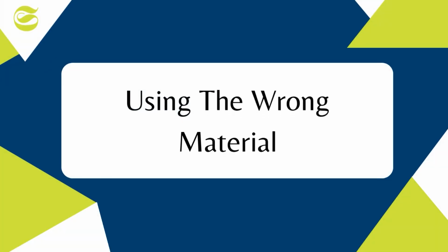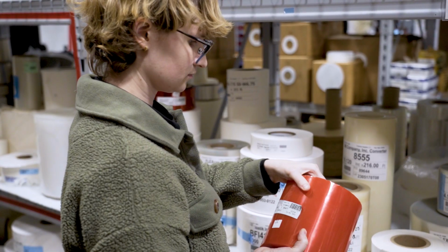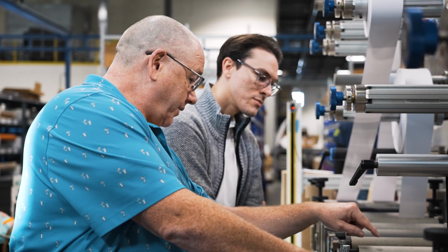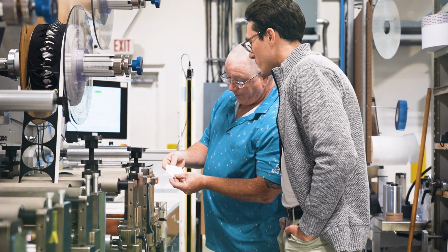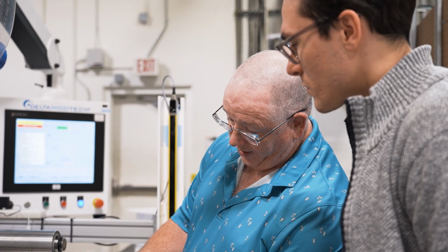Third, using the wrong material is a common mistake. Some materials make it more difficult to maintain tolerances or can react poorly under production conditions, causing instability or defects. Other materials perform fine in sheet samples, but they have full-scale production limitations. If the material selection is not aligned with the manufacturing process, it can lead to a lot of issues. A knowledgeable converter will take proactive measures to address potential material challenges. For instance, if your design involves a 3-layered part made entirely of highly flexible materials, a converter like Strouse may suggest incorporating a more rigid material into one of the layers to help ensure smoother and more consistent production.